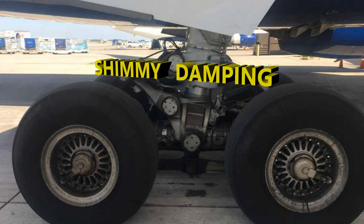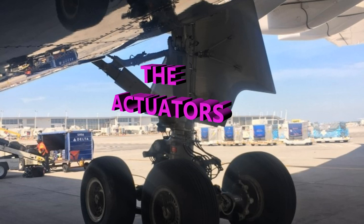Okay, all right, now let's talk a little bit about the actuators, since I did mention them. Like I said, there's two. They're parallel to one another, and they're operating around what's called a rotary collar. What it's doing is giving the steering rotation. That's why you have the rotating collar. The actuators are attached between the upper and the lower flanges, and the rod ends are attached to the rotating collar. So it's transmitting that movement to it.